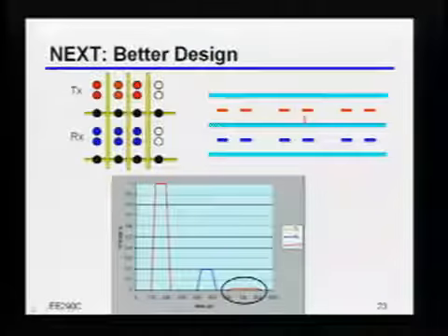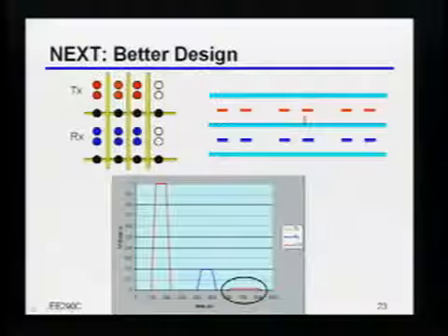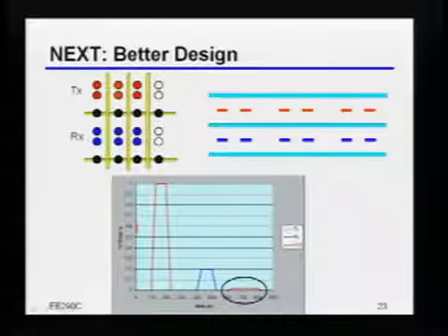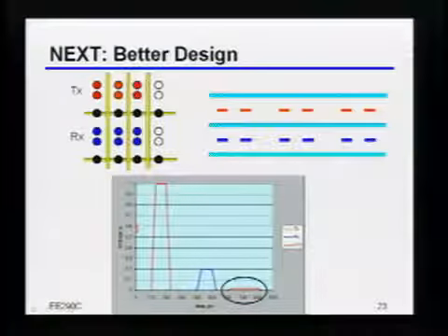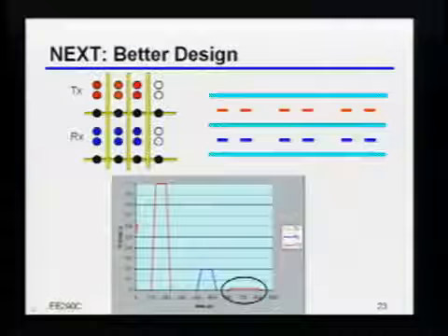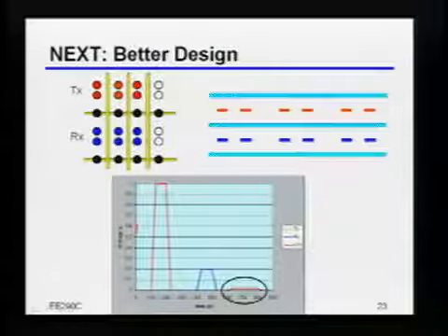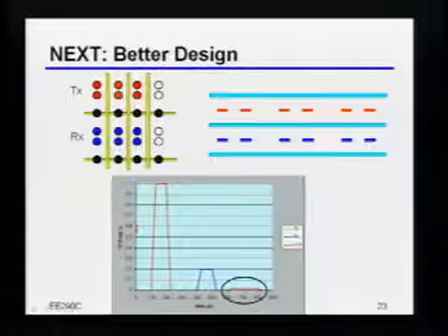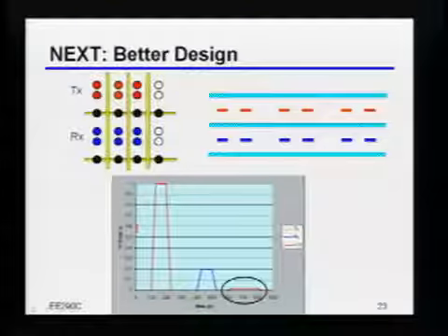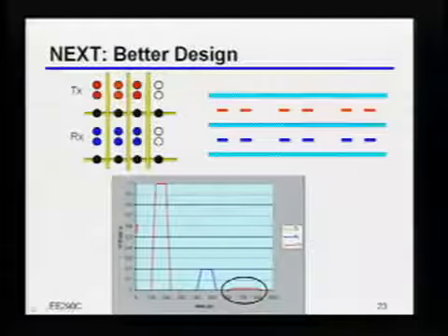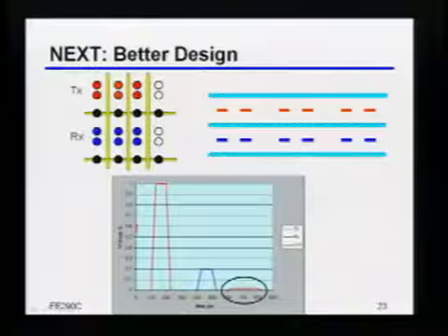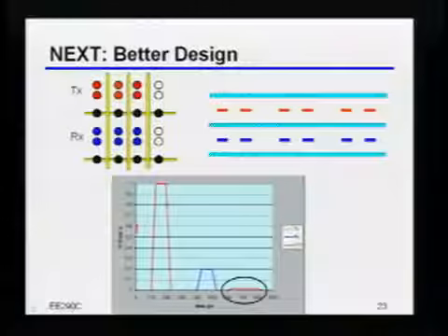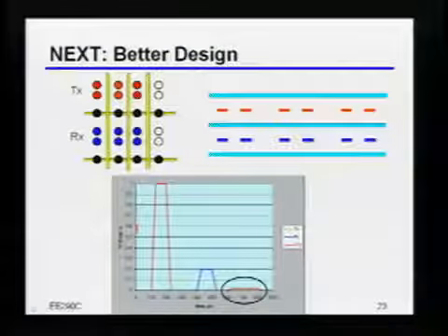Okay, great question. You were asking, is there something you can actually do on the chip? You want the flippant answer or you want the technical answer? Either way. Okay, the flip answer is that it's painful. The technical answer is yes, indeed. If I knew what the crosstalk was, and I had my transmitter and my receiver and another transmitter and another receiver, and I knew the data that I was going to be transmitting, and I knew that it was going to hit my receiver, indeed, you could do crosstalk cancellation or crosstalk correction or something of that nature.